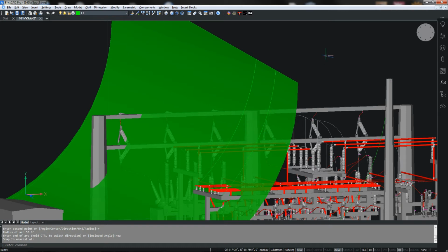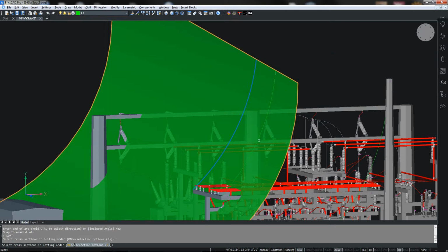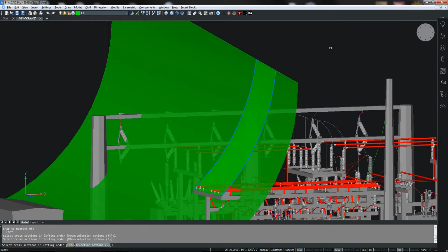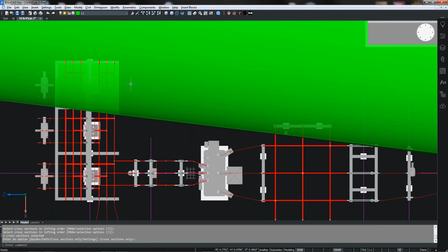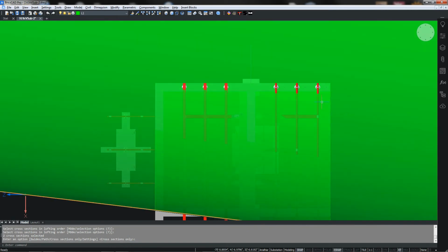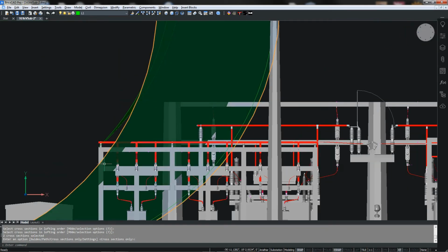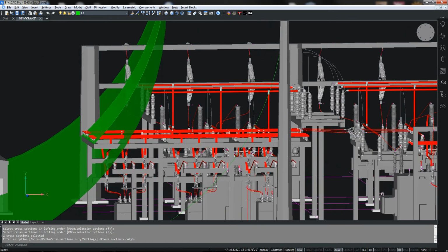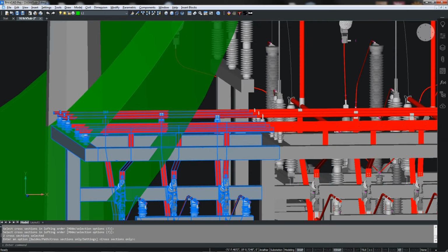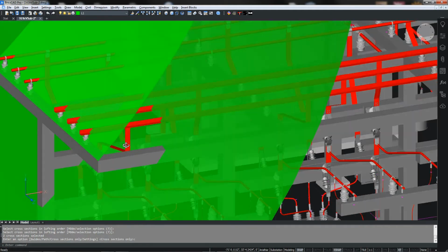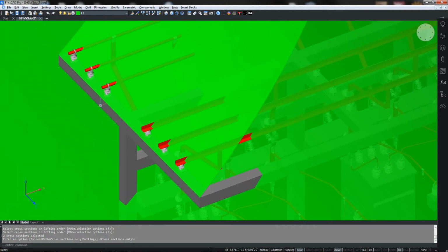new arcs, and so we want to again use our loft command. We want to loft from the last arc to this one, and now you see that we have increased our coverage to the point, and all we lack, as I pointed out a while ago, is on the end of these, because you have your surface that obviously ducks underneath these to get to that point. Here's my solution to that. You might find another one.